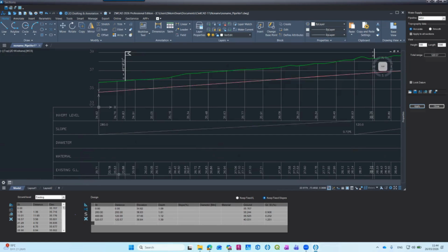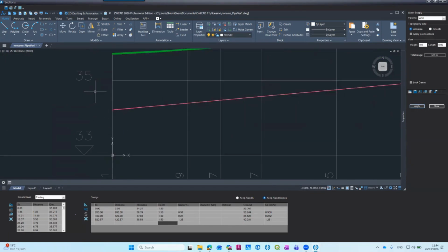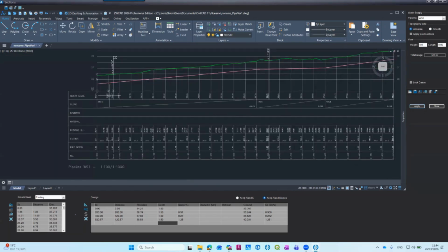as you know, is shown in the table, right? The breaks. But the depth is not actually 1.5 because I did it more or less. So I would just take all of this, convert it to 1.5 meters with the same station, press enter and apply. And now it's exactly 1.5 meters here, 1.5 meters here, 1.5 meters here, and 1.5 meters here. Good.